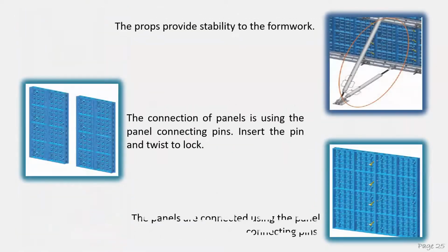Okay, in any types of formwork system, you can see that they use bolt and nuts, konsep dia to make sure that this all formwork, especially between the panel, is very close enough to ensure that there is no any concrete leaking during the concreting work, and also to avoid the concrete being overflow in the formwork.